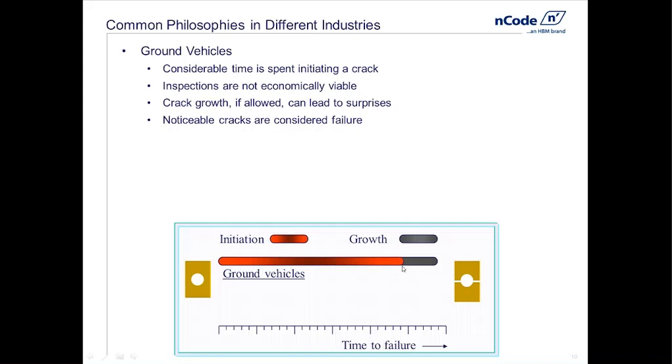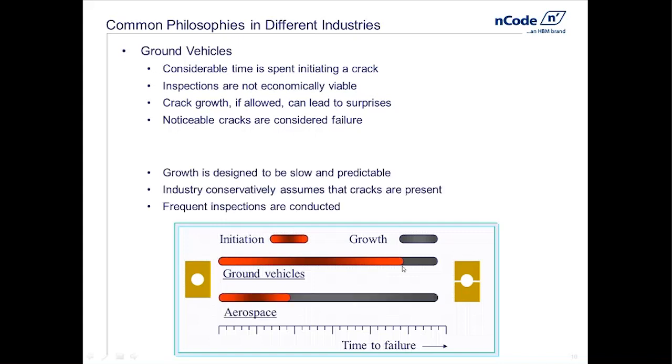In contrast to that, on the aerospace side of things, many components are made of tough, or what we call crack-tolerant materials. Toughness, by definition, is the ability to be strong and ductile at the same time. You think about the area under the stress-strain curve as being like energy. So the more ductile and strong a material is, the more energy it can absorb before failure.